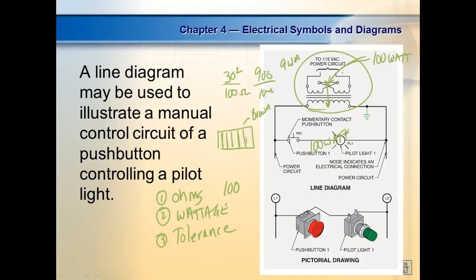So if I'm going to electronically control AC, then I convert it to DC, and then I can use DC to regenerate an AC, right? You understand? But now the AC that I'm regenerating, I'm doing what? I'm controlling it, right? You understand that? So that's the big advantage of AC, is that we can step it up and step it down. Plus, it induces the voltage in the motor, so we have what we call induction motors, in which one of the magnets is actually induced.